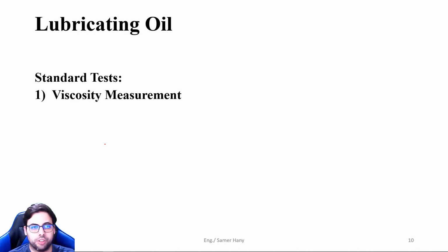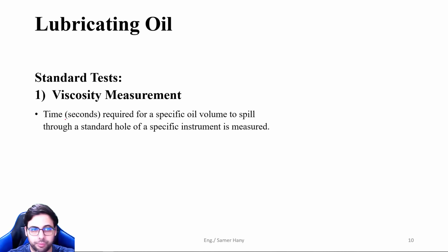Alright, so let's dive into the standard tests that we want to conduct to check that the oil is according to standards. First test will be the viscosity measurement. And this viscosity is measured as the time in seconds required for a specific oil volume to spill through a standard hole of a specific instrument.